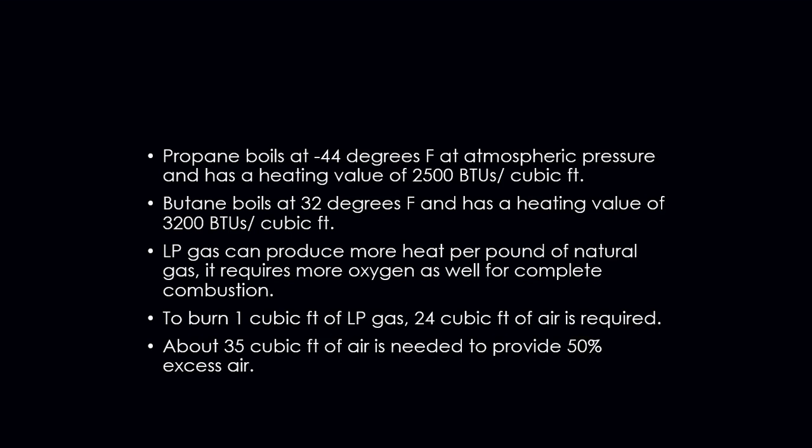Propane boils at negative 44 degrees Fahrenheit at atmospheric pressure and has a heating value of roughly 2,500 BTUs per cubic foot. Butane boils at 32 degrees and has a heating value of roughly 3,200 BTUs per cubic foot. LP gas can produce more heat per pound than natural gas. It requires more oxygen as well